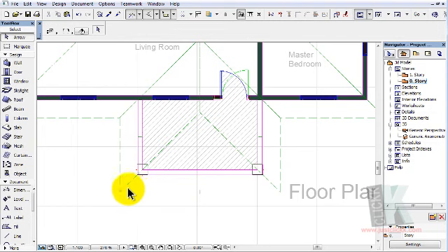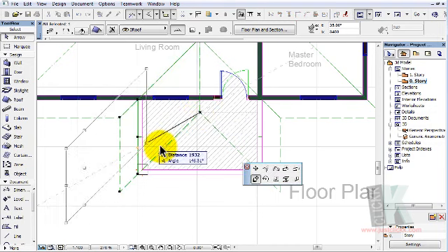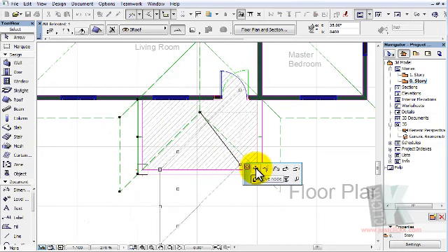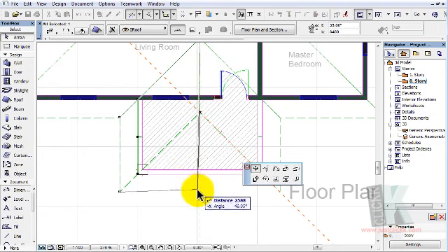You will delete it, yes. Once that is done, you click this face of the roof and then click on this node here. While you click on the node, don't move around. Make sure you take a look at the palette here and select move node. So you are targeting this node, and after selecting the node, you now move it down to sit around here.